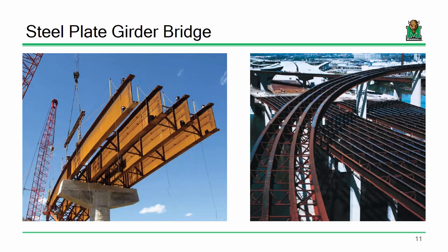Another thing that's kind of interesting about this, and I'd say this is a unique aspect of bridge engineering. Structural engineers tend to deal with mostly buildings and bridges. And I would argue that with bridges, what can be more critical through the design process is the concept of staged construction. We've got this bridge. The first thing we do, we set the beams. We connect the cross frames. Then we set our formwork. Then we pour the concrete deck. Then the concrete deck cures. That construction process happens in stages.